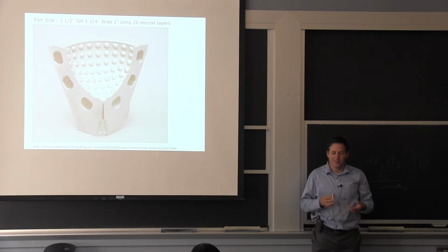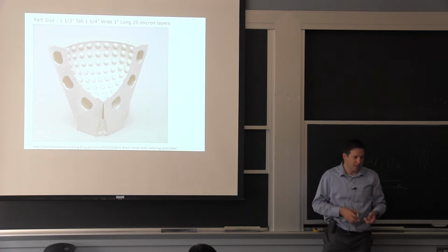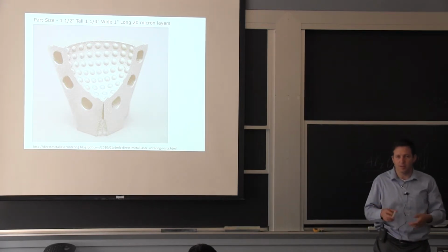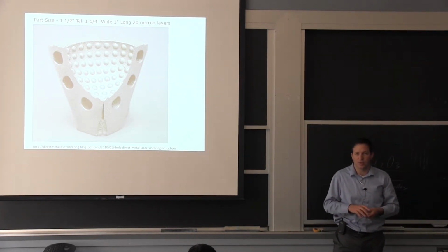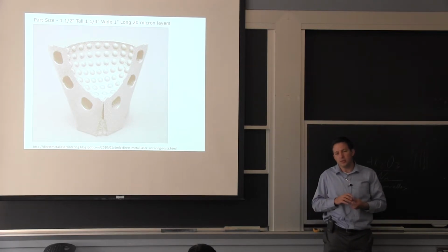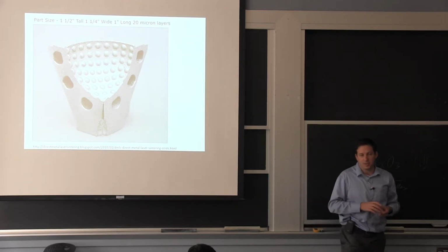But they're still working on it, because if you're going to try to do this process here and melt platinum, it's very, very high temperature. You get a lot of distortion, so there are issues. But definitely you can do it by 3D printing the mold and then doing a casting of that. So it is done quite a bit these days.